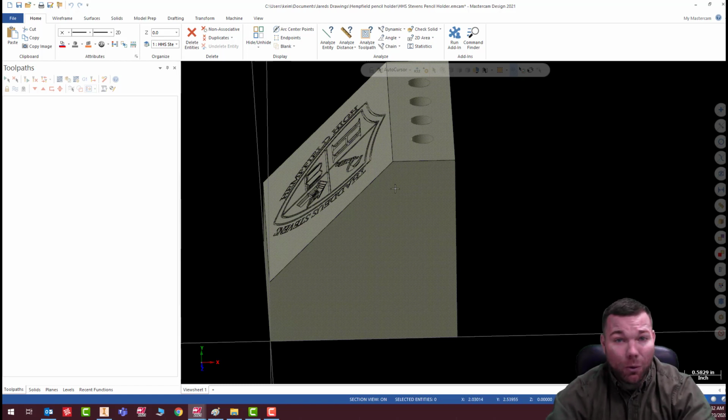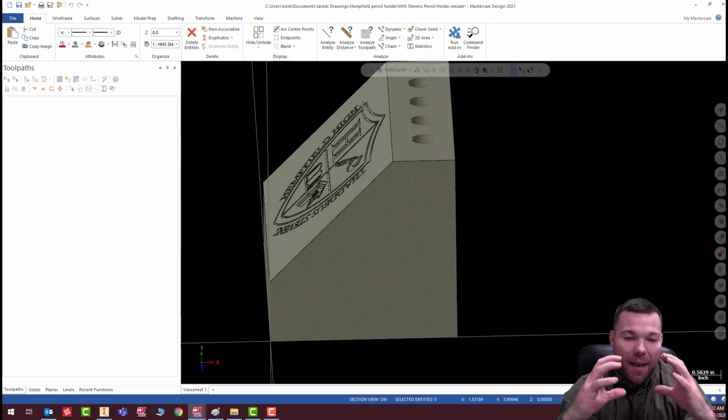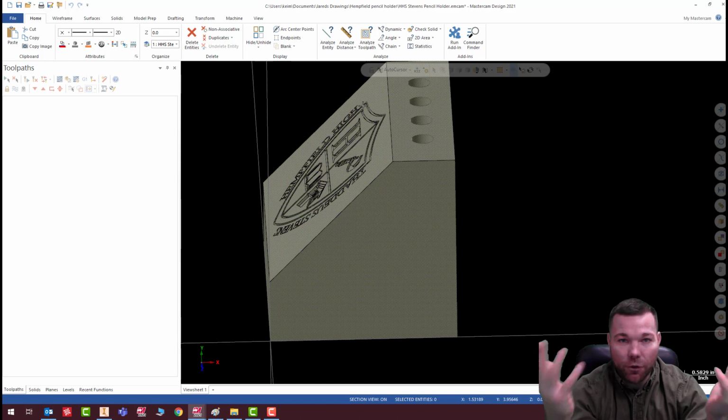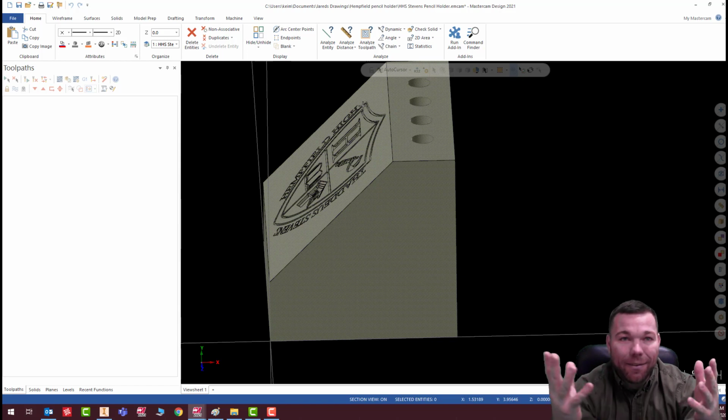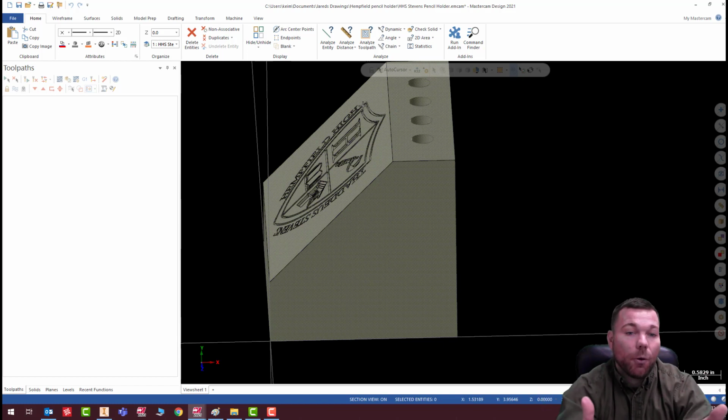So I have to order 3¼ by 3¼ if I can get that. More likely, probably 3½ by 3½. So basically what I'm getting at is you could save material by making this and forming it a little bit smaller. It'll still work just the way it does now, but you would save that material. Now, that might be 10 cents of material, might be $1 of material. But think about over 10,000 parts. If we were making a large quantity of these, 10,000, and say it's $1 per piece of material, that's $10,000 you just saved across the job. So just something to think about.